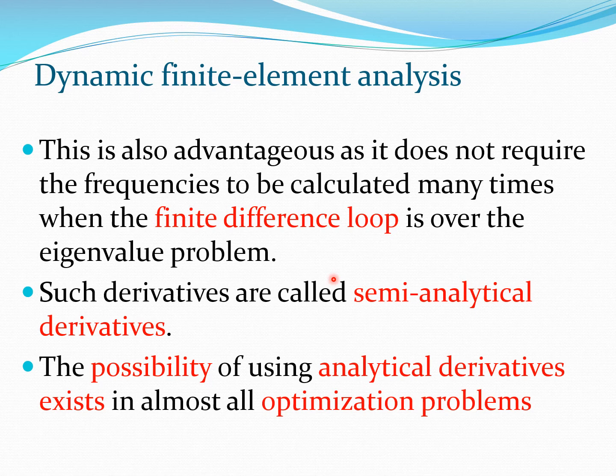So just like I was telling before, the advantage of this method is that you do not calculate the frequencies in a huge loop and do finite differencing. And even in finite differencing, as we have mentioned before, there is room for various problems because of the selection of the step size. And you may need to use the central difference formula in some cases. So all that is mitigated by using these kind of derivatives.